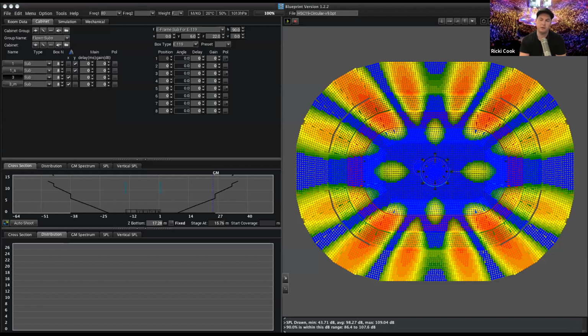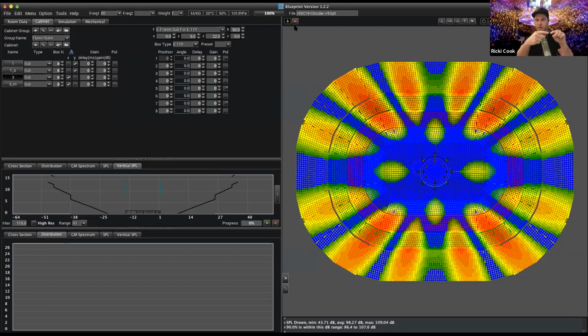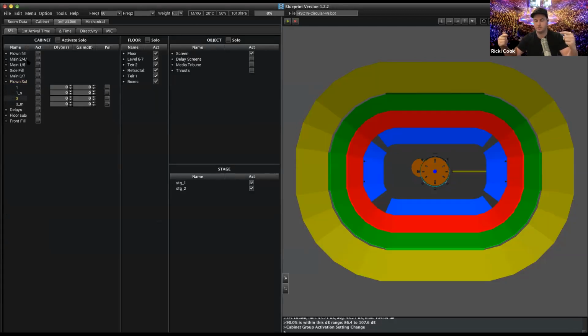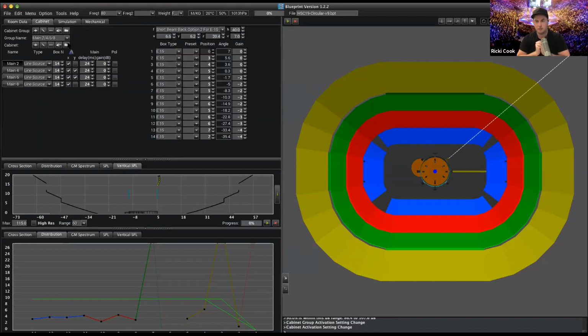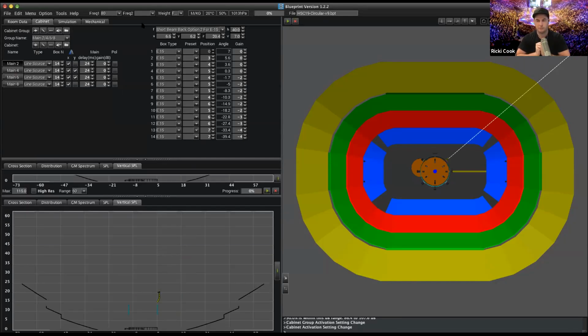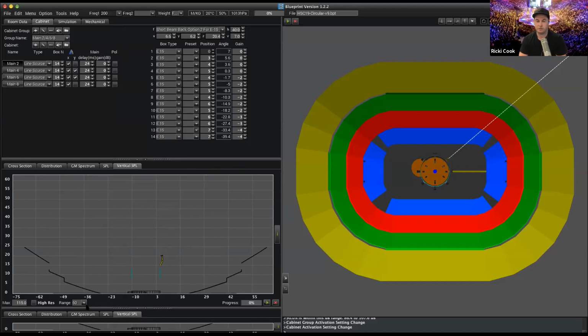It's the same as when people do in the round, and it's more of an oval shape, and they'll put 2 subarrays at the very end. Energy firing backwards from each sub will cancel out other energy at each end, and then in the middle at the sides, you'll get this like 6 dB increase from both arrays, and it's overwhelming. I've seen that before, and it's ugly. And you can talk about cardioid until the cows come home, but in an arena of this size it's not going to matter that much. The other thing you need to look out for is the reflection off the walls coming back as well, because you've got to account for those.